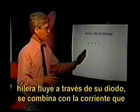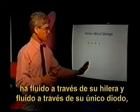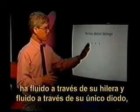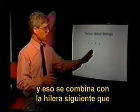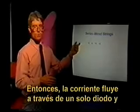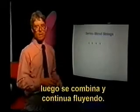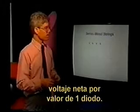Current from one string flows through its diode, combines with current that has flowed through its string and flowed through its single diode. And that combines with the next string, which flows through its single diode, and so on. So current only flows through one diode and then combines and flows on. So we still only have a net voltage drop of 1 diode's worth.